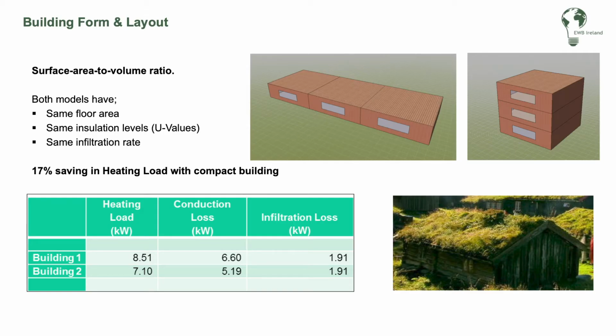So a general principle of passive design as well, things like living spaces, put them to the south. Circulation spaces, toilets, kitchens, storerooms to the north, because they act as a buffer zone to the colder northern climate. And an issue can be, especially with west-facing kitchens, because of the low evening sun and people are cooking at that time of the day, it can cause overheating.